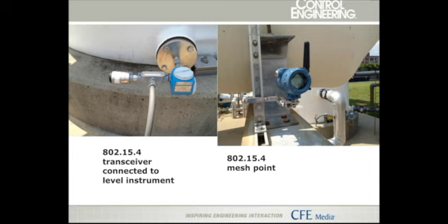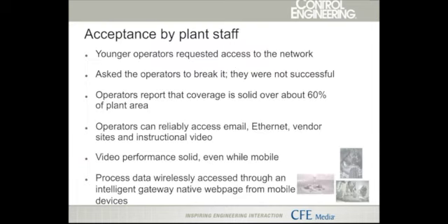What I forgot to mention was the sensor network, the WirelessHART network, also forms a mesh network. So if you have something that's blocked, say, with a large metal pipe or wall or some device that inserts attenuation, then using a properly placed WirelessHART device will allow an RF path back to the gateway.